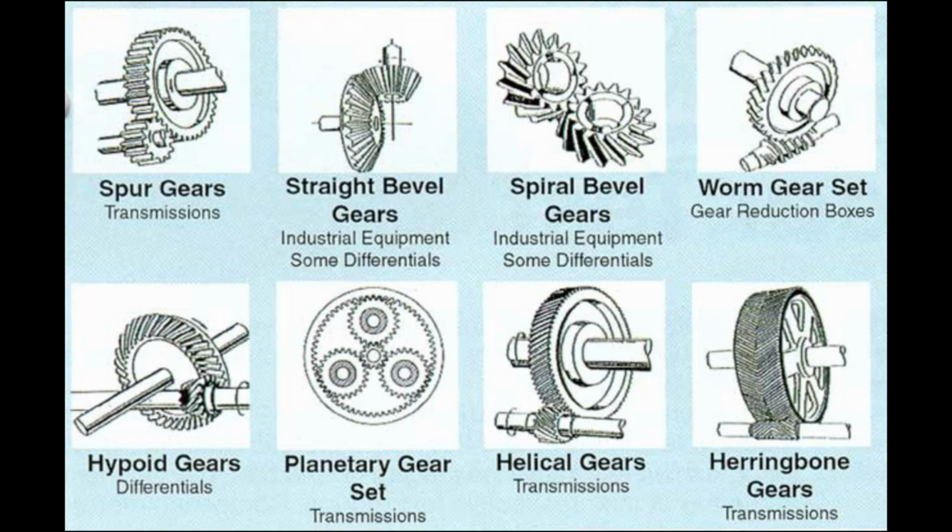Gears are the fundamental components in machinery. They are used for transmitting rotational motion along different parts of a machine. Depending on the gear ratio and its type, the gear could change the speed, force, or direction of a moving component. Gears can exchange torque, which is the amount of turning power it has, for speed. Gears that provide more torque generally take longer to rotate compared to gears with less torque.